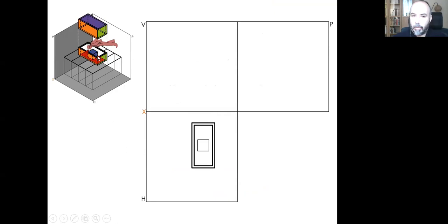There is the bottom surface of this rectangular prism with the lines here. We can draw them. They are the objects that we see. Again, they are not cut. So we need to use the same middle thickness, middle darkness, and continuous lines in order to create the lines on the bottom surface of the prism.